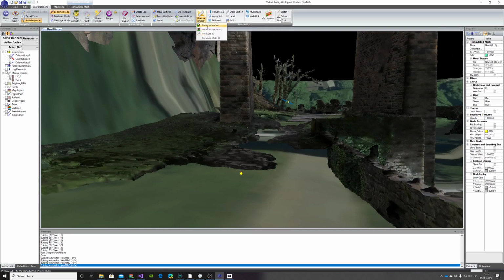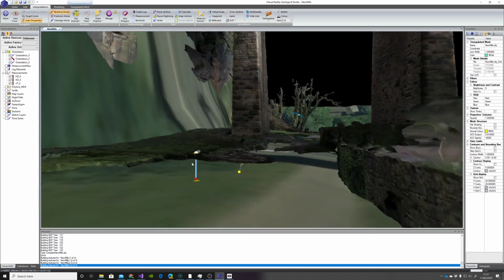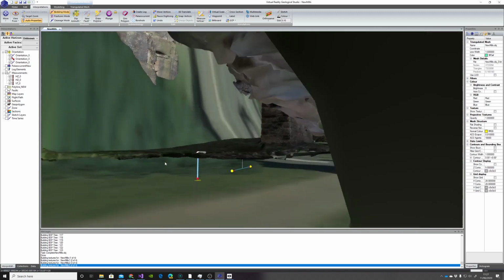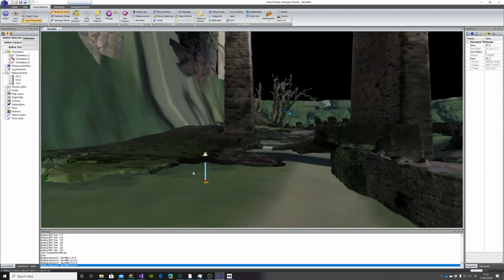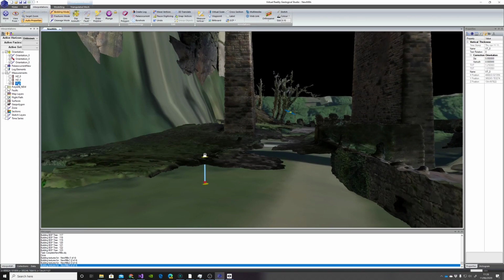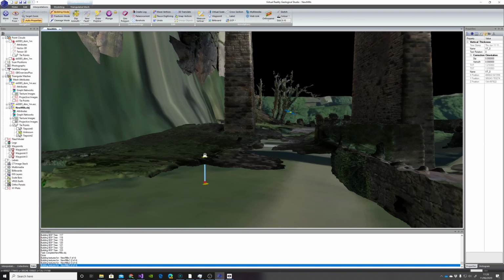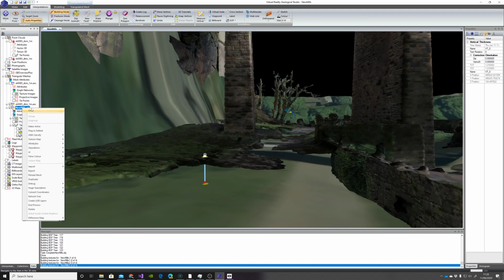So measure vertical. There we go, that's a bit better. Now, the measure vertical tells me that the vertical distance here is 1.2 meters. So I need to subtract the offset that we've got from this vertical measurement, the 1.2 meters, from our structure from motion model.